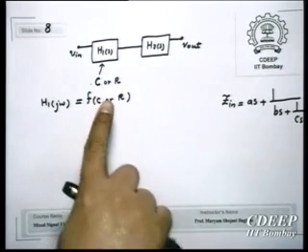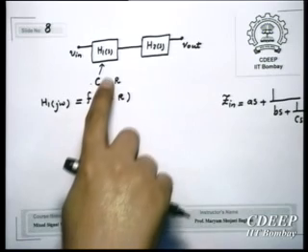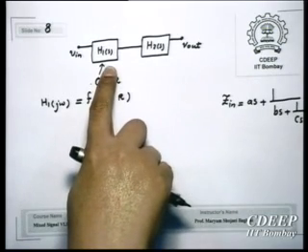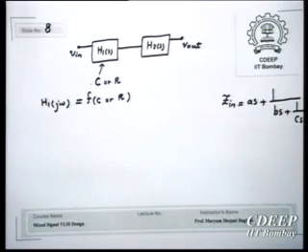But again, this is not working for on-chip implementations, because in on-chip implementation you cannot say I have a capacitor here which changes with process, and here it doesn't change. Therefore, in a cascade of filters, because all parameters are changing, effectively you may see a similar problem to that observed in the case of ladder filter if it is not with minimum rho.